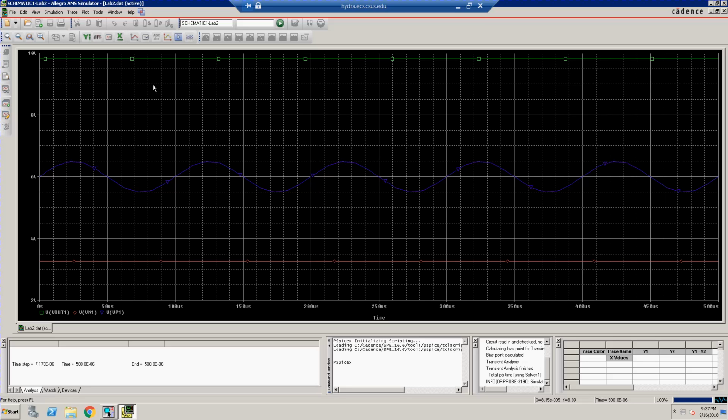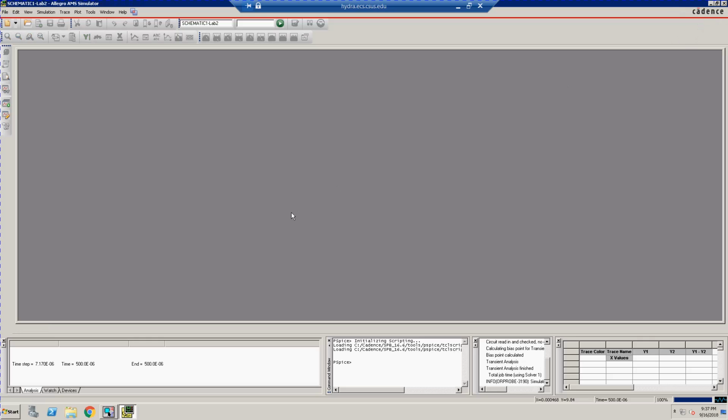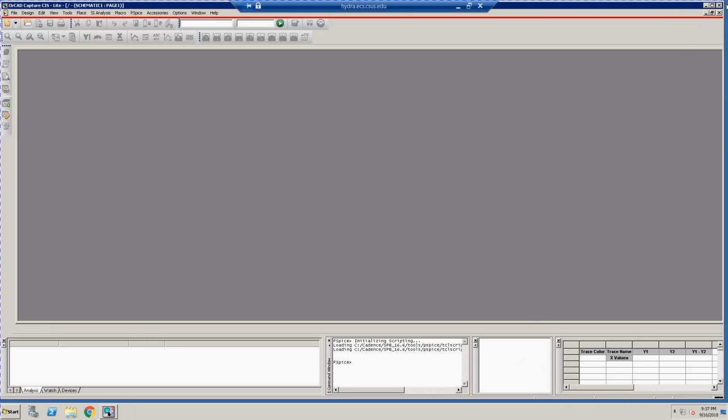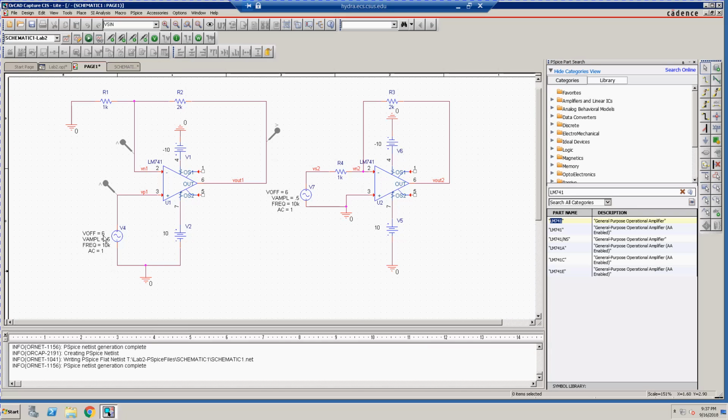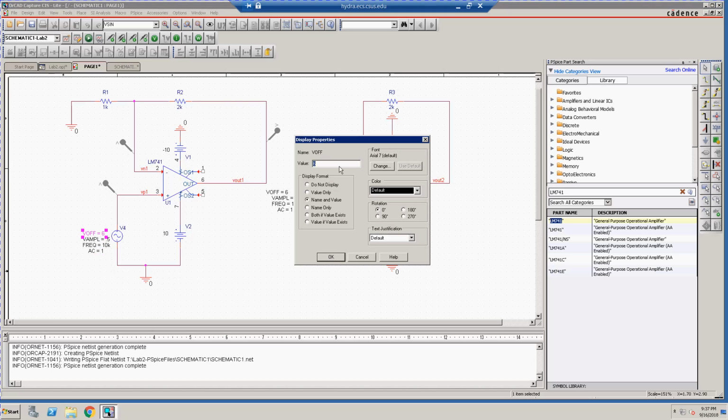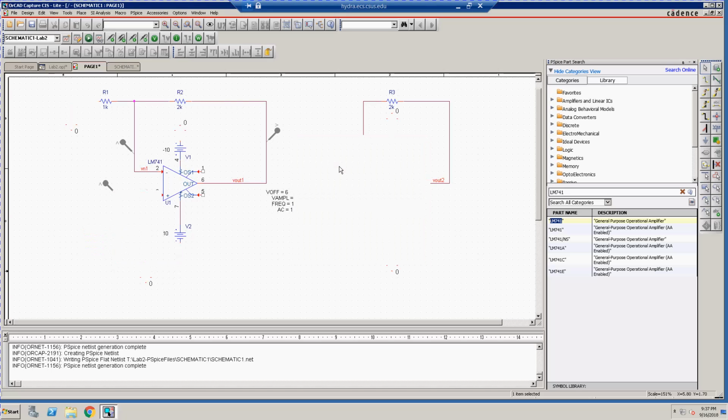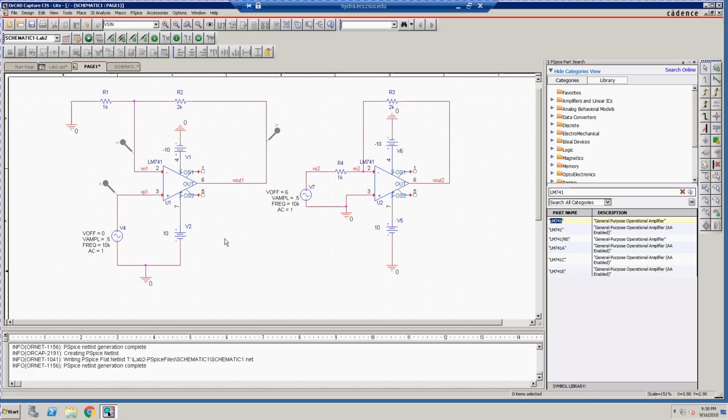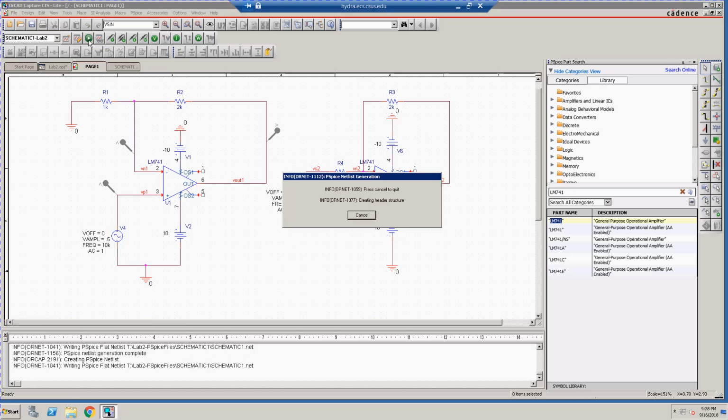We'll notice that VN1 and VP1 are flatlined. That might be because of our bias condition being at 6 volts. So let's come back here. I'm going to make a quick change on that. I'm going to put our offset, or DC positioning of our signal, right in the middle at 0. Save that. And we'll go ahead and run it again.